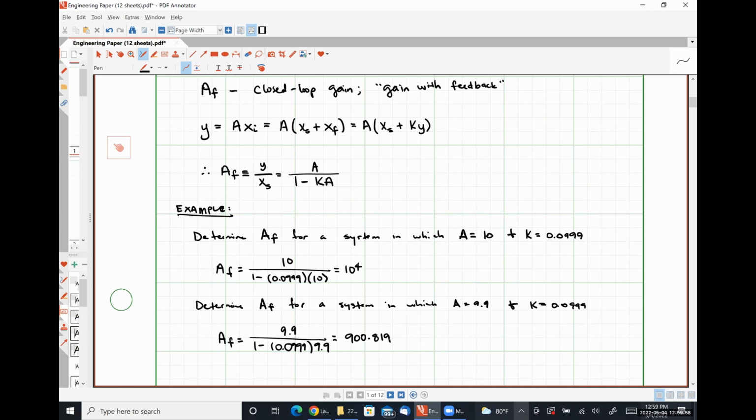So it's for these 3 reasons, right? Gain sensitivity, system instability, and noise amplification that, typically speaking, positive feedback circuits aren't used as amplifiers, right? Effectively, we corrupt the output signal whenever we have positive feedback applied.